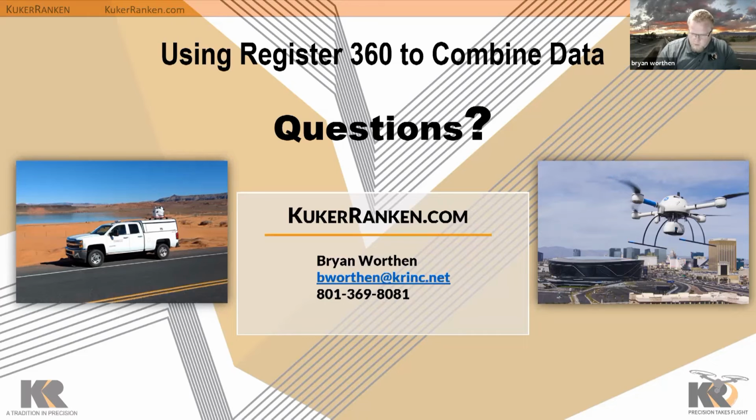So the control points, I shot those in with my GPS, GS18I, and those I had tied to targets, which I used in the P40 data. And so from the GPS side, I just exported a CSV file, northing, easting, elevation, and imported it into Register 360.